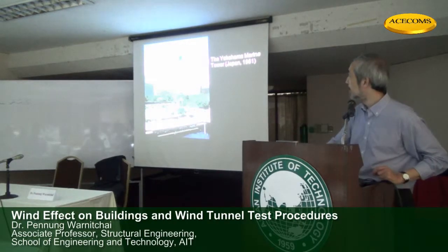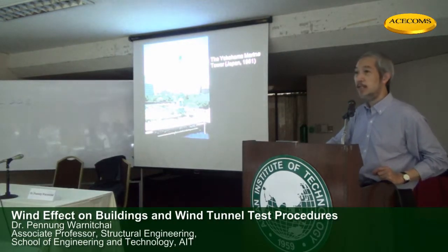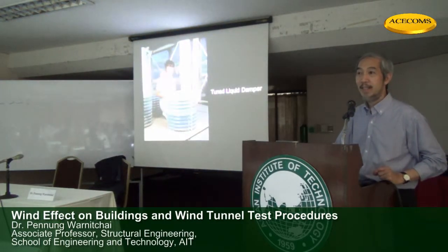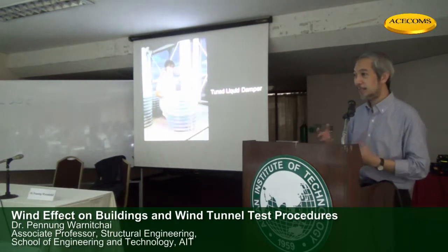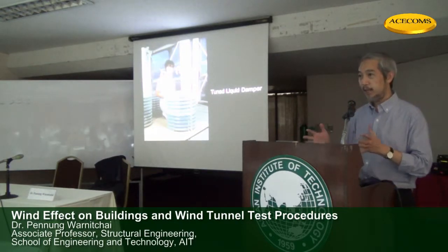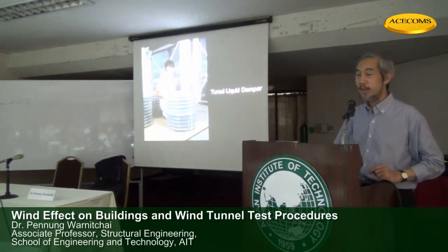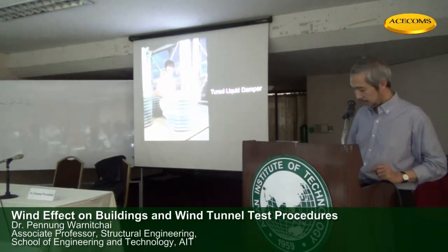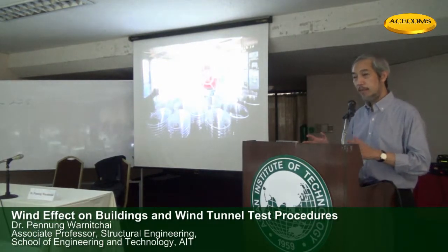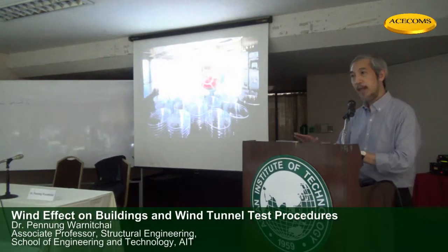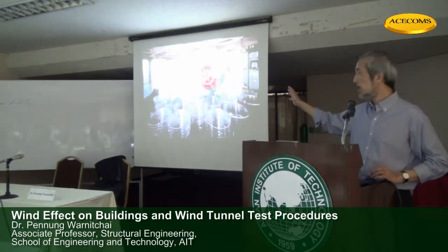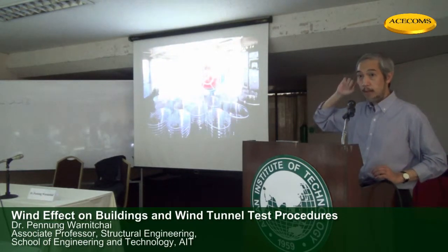This is more interesting. It's the Yokohama Marine Tower in Japan. They adopt this type of damper. No mass spring, no viscous damper, just plain containers and water. And it can work. It works if you put enough of them like this. You have many of them. When the tower moves, the water sloshes and produces a counteracting force. It can reduce the vibration down to around 30% of the original level.